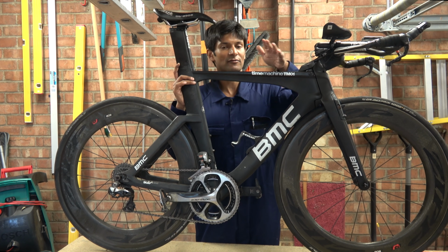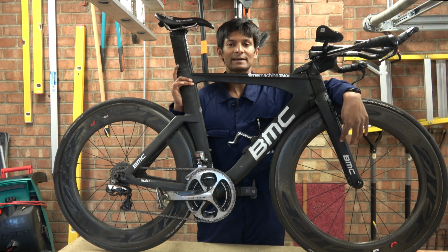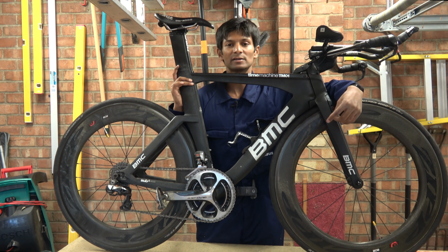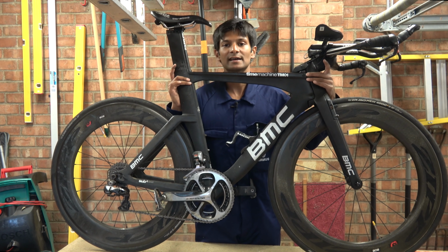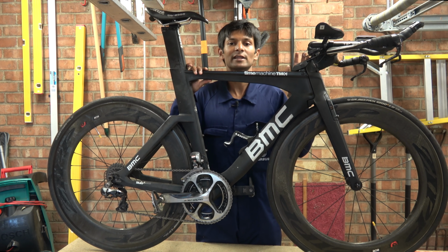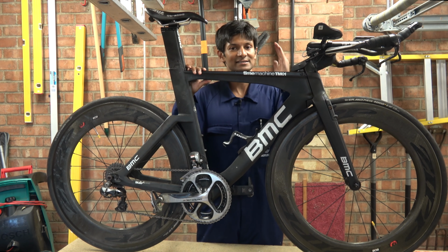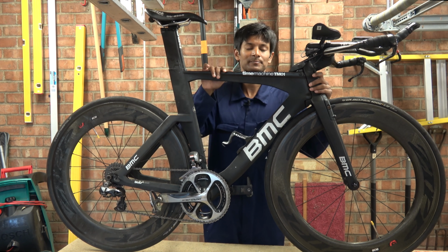So if we just go from front to back, the front wheel is biased towards radial loading, but there's also a bit of axial loading when you go around a bend. The headset is predominantly axial. The bearings in there will never do one revolution in their entire lifetime. So they are designed for an axial load, which is basically into the bearing.